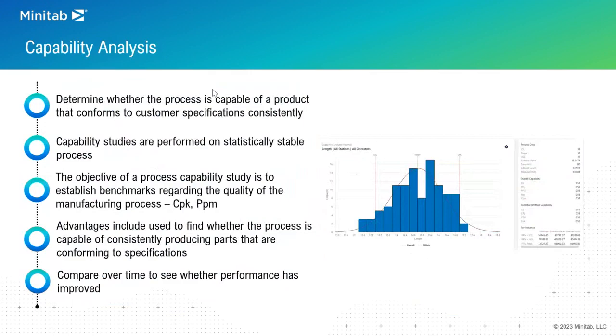Measurements tend to cluster around the middle of the distribution with less data around the tails. That's what a typical histogram for a good process would look like, a bar graph that shows the amount of variation in the process itself. When that distribution does not follow the normal distribution curve, an assignable cause has come into play. So now you're looking at the specifics of your measurements and the frequency of those measurements to understand: are there any assignable causes that have come into play?